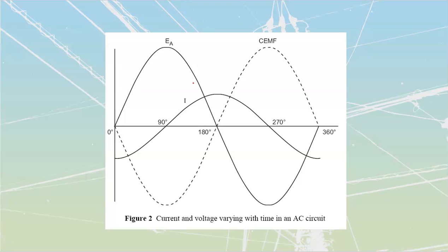The other thing that we need to take a look at is, what does an inductor oppose? It opposes change in current. So we know that counter EMF has a formula: E is equal to negative L delta I over delta T. Remember, that's that formula that was missing all the deltas earlier? This is going to be the formula for counter EMF.